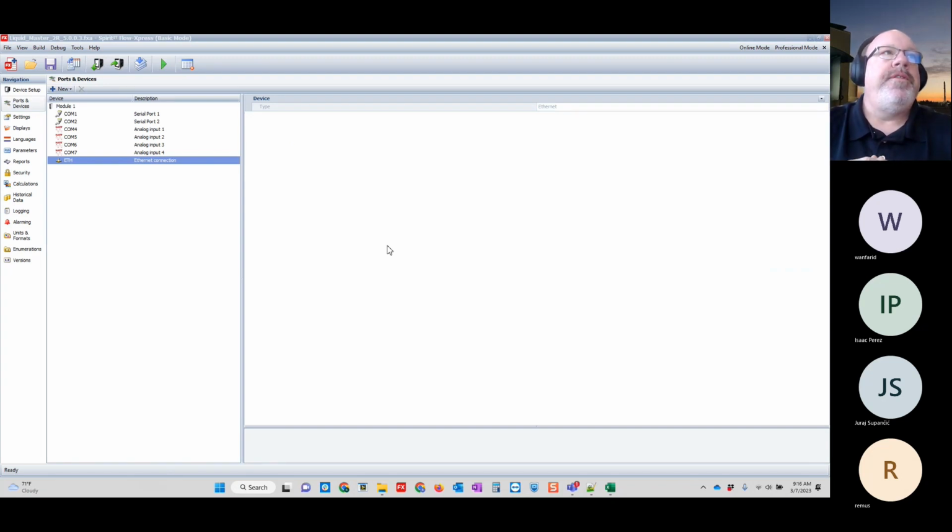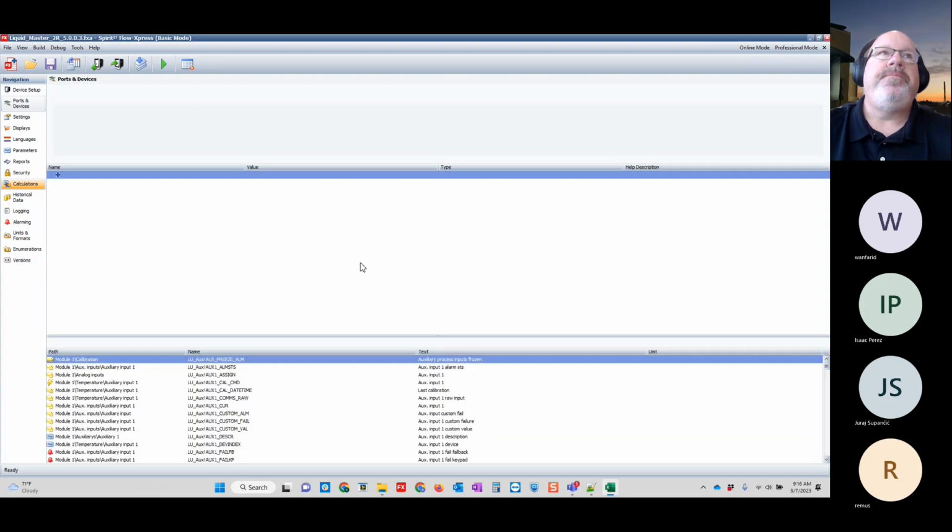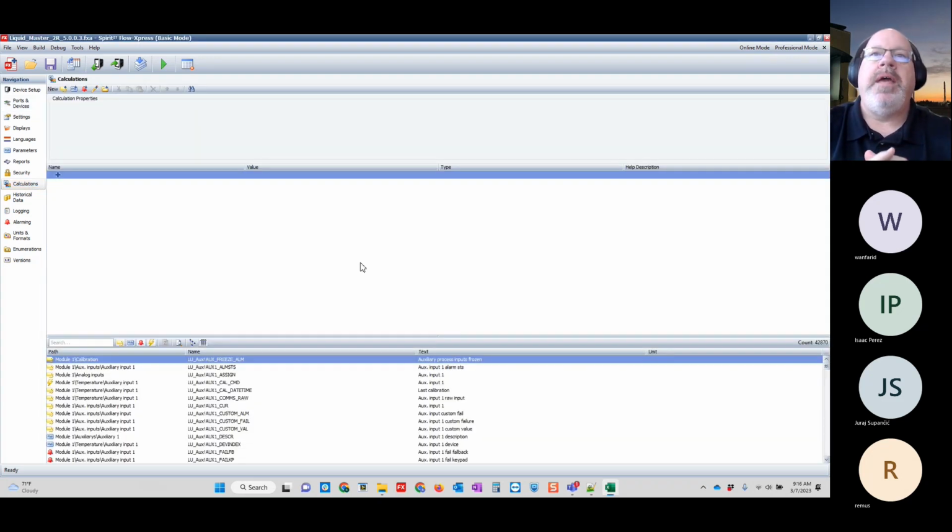So what we're going to deal with is a section of the FlowX that's called calculations. Calculations were meant to be able to build tags, build commands, or build logic in the FlowX that isn't inherent to the application, but allows you to do some of your own custom logic. Now, a lot of this logic is just simple Excel logic. If, and, or those types of statements and so forth, you can utilize that terminology or verbiage inside.